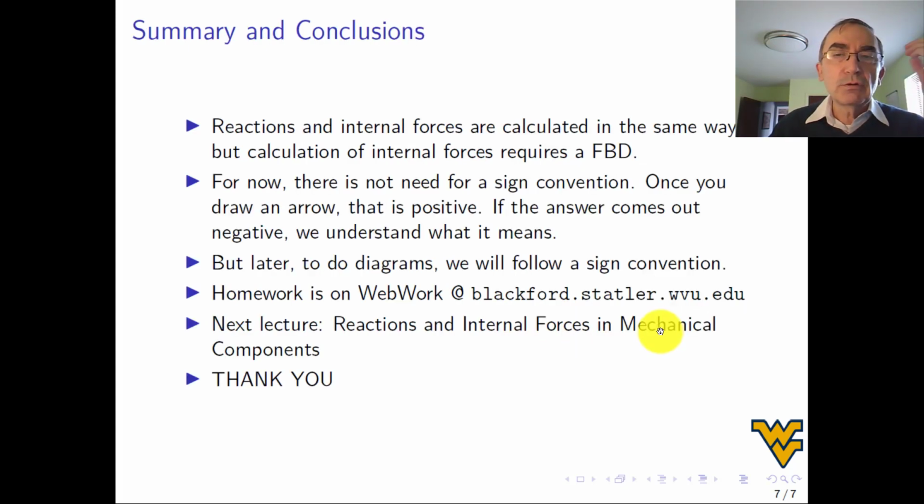All right, so for this lecture, we have some conclusions. The reactions and the internal forces you have seen are calculated the same way, but the calculation of internal forces requires a free body diagram. And for now, there is no need for a sign convention. Once you draw an arrow, that is positive. If the answer comes out negative, we understand what it means. There's no problem. But later, to do diagrams, we will follow a strict sign convention. There will be homework assigned on web work at this address.